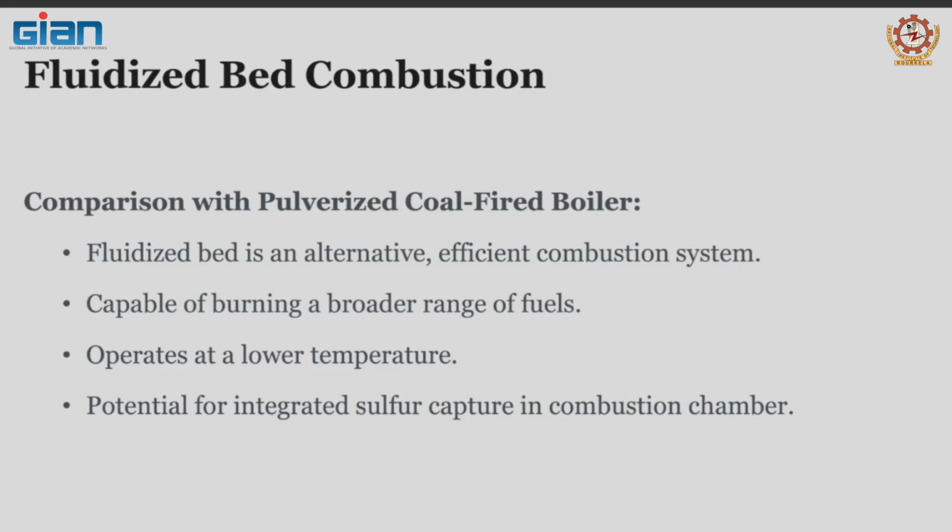We have an efficient combustion system. You have a much broader range of fuels you can burn in fluidized beds. It operates at lower temperature, again a big advantage, especially from the NOx perspective, and it also has an integrated sulfur capture in the combustion chamber. What does this mean? You will see in a minute.